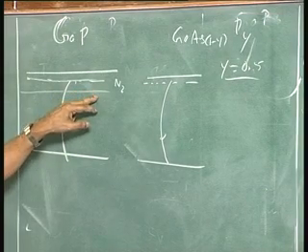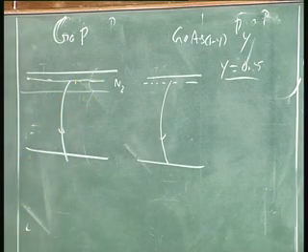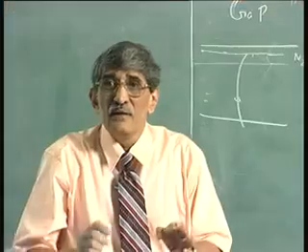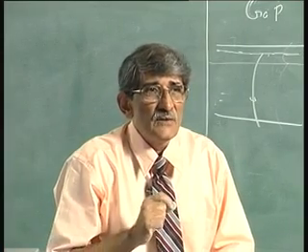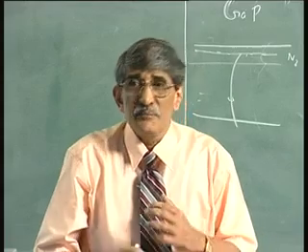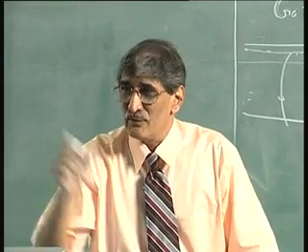If I have one more impurity, what will happen? There will be some transition through this, so you will have unwanted emission. So, that is why when you make light emitting diodes, it is important that you have a pure material. The growth must be really pure, and you must be able to introduce the impurity which you want to introduce.